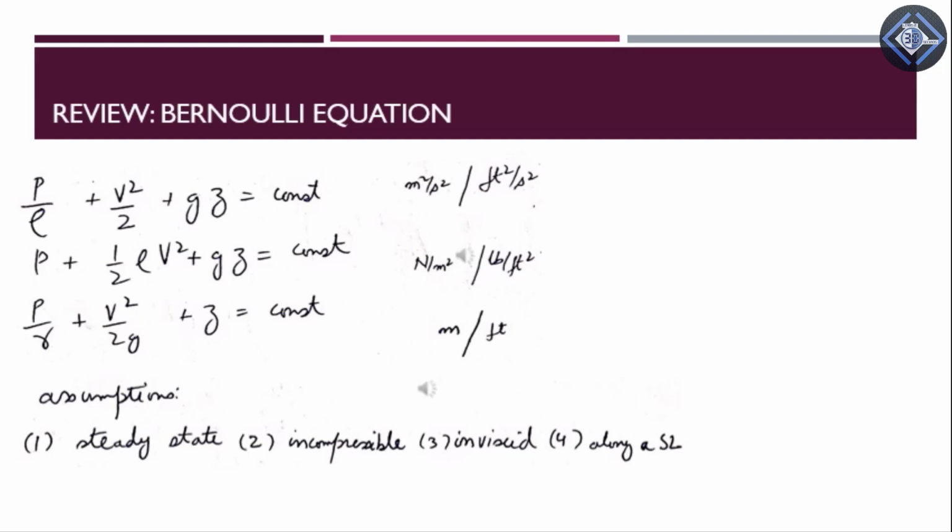So we must make sure that we apply Bernoulli equation when we can assume the flow to be steady state, incompressible, inviscid, and along a streamline.